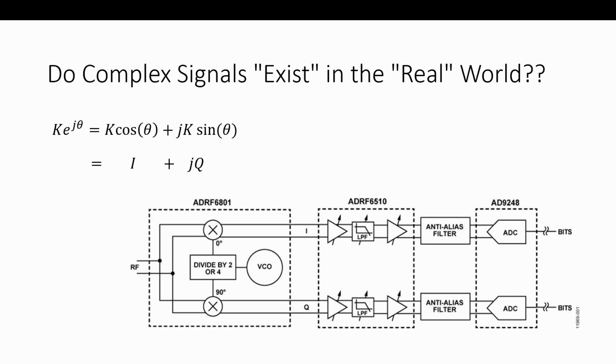The way I visualize it, when I'm thinking of these things in my head and getting to the intuition, or when I'm doing the analysis on paper, I'm completely treating each complex sample as a single number. So e to the j theta is great as a representation and makes life a lot easier. Then when the whole block diagram collapses down to its simplest form and I go to build it, I will break that out into its I and Q components.